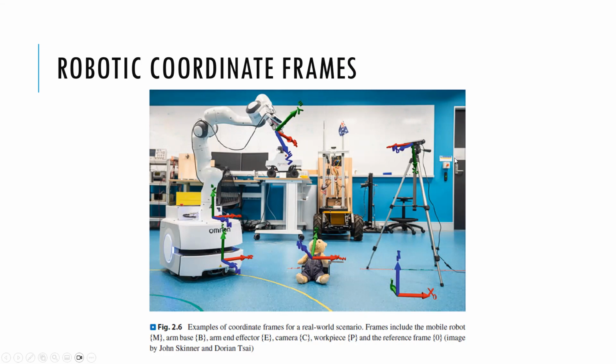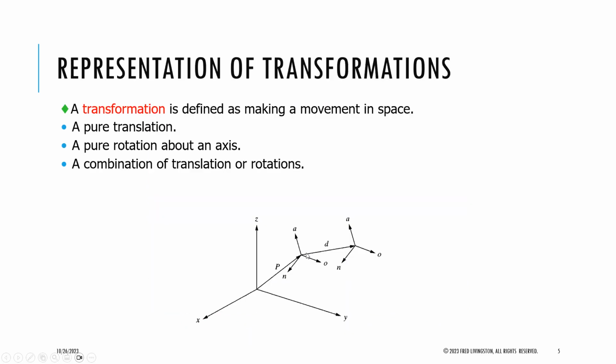For example, if I want to go from the base frame to the gripper to see this object here, if the camera sees this object, the transformation from the base to here, to here, to here, would be the same thing as from here to here. But you also use the camera here to detect that. So there are multiple paths of finding that missing information, and so we also have redundancy in the sensors when developing that transformation.